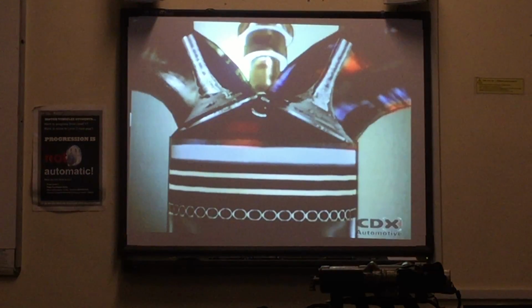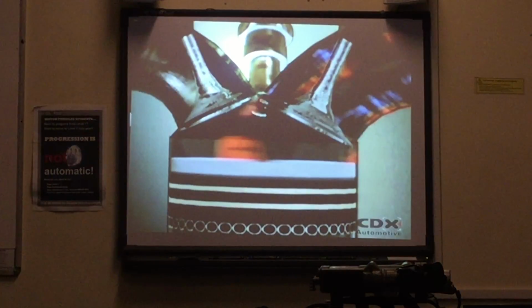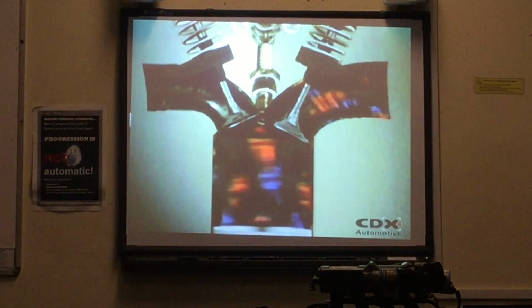Let's look at a simplified model. The intake stroke starts with the exhaust valve closed, the inlet valve opening, and the piston at its highest point, top dead center. It starts to move down, increasing the volume above the top of the piston. This makes the pressure inside the cylinder lower than the pressure outside. This higher outside air pressure forces the air-fuel mixture into the cylinder.